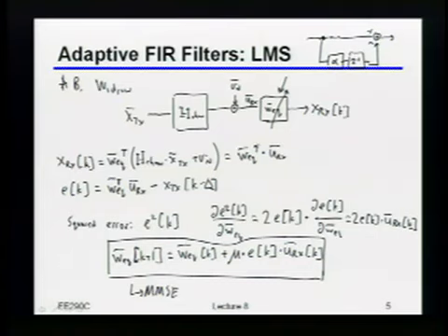When I do this update equation over here, I really just have one coefficient, which is this alpha value. But in order to find that alpha value, I have to correlate the current error with essentially what came into the equalizer one bit ago. Does that make sense now?